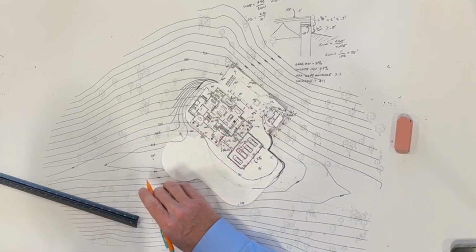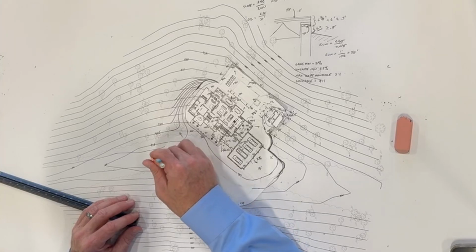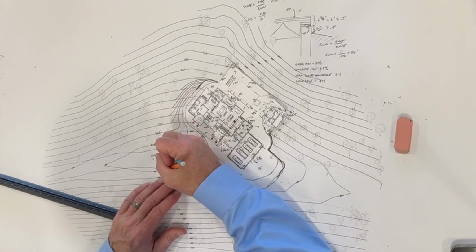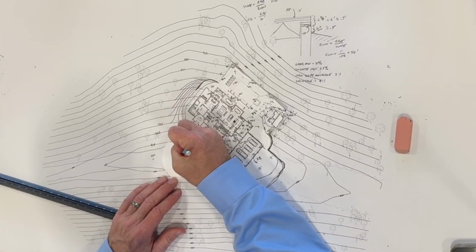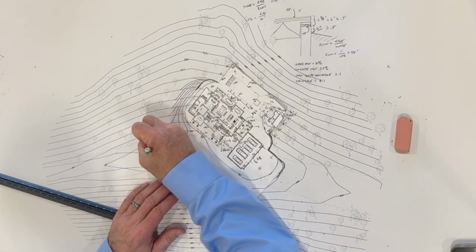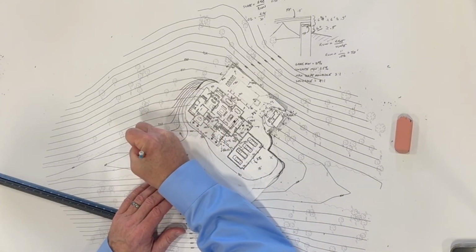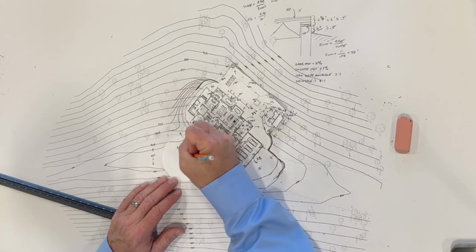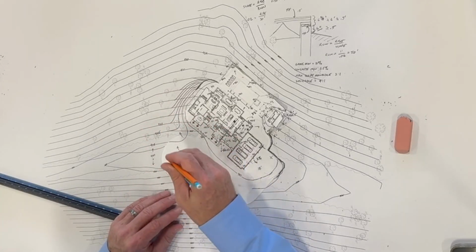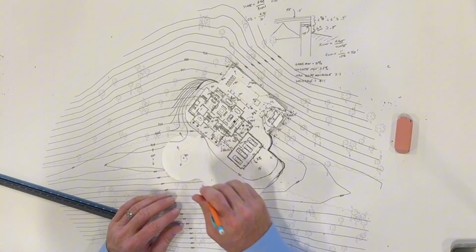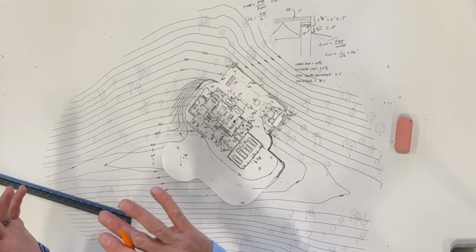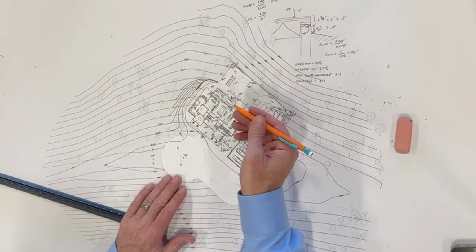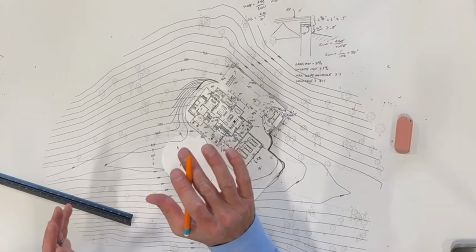Now here, we go back over here and we've got a 940 just in that one spot. And here's the 939. Let's call this a 940 as well. And you can do this because the water is going to be sloping in this direction, right? And that'll be the high spot. Now that'd be kind of neat, I think, right? Because you can do a statue or something in the middle of the island, landscaping or something. It'll be at the high point with the home behind it 2 feet higher. So as you pull up, this is going to look really good.